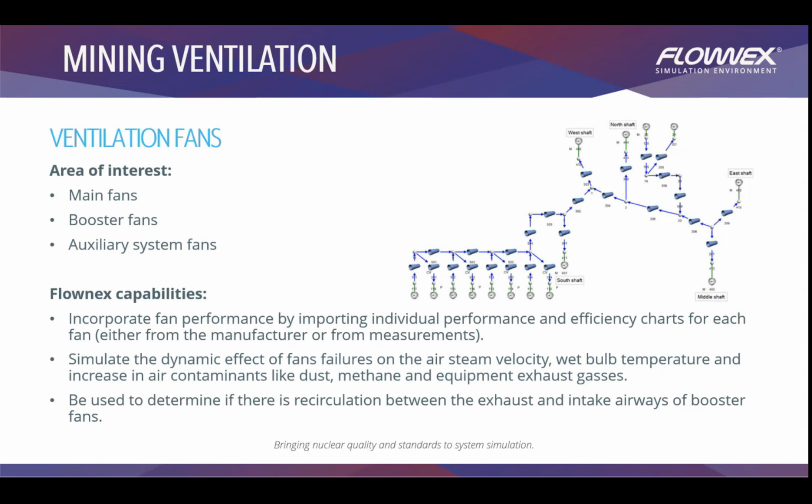For example, some rooms will need more cooling, some rooms will need less cooling. You can do that in Flownex as well. And you can see on the top right, there's a pipe network that we have out there. So we can use the air network to explain the water distribution. We can have a simple pipe network, just the one that's on the top right, where we're moving water from one end to the rest of the ends, where we have different requirements of the flow.